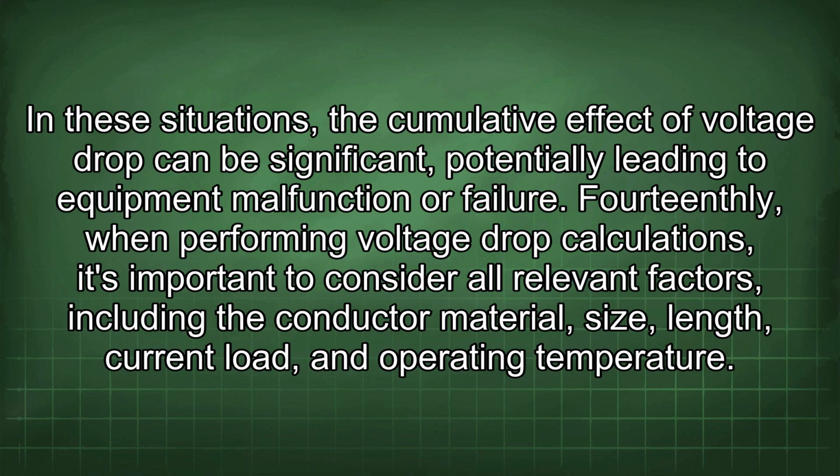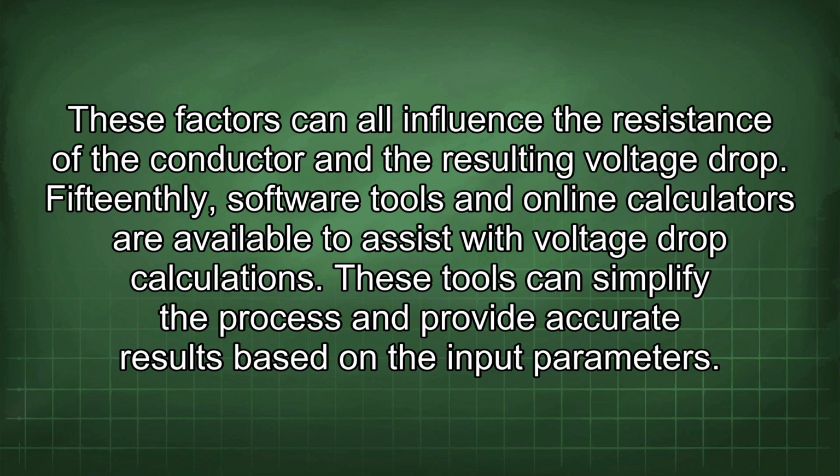14thly, when performing voltage drop calculations, it's important to consider all relevant factors, including the conductor material, size, length, current load, and operating temperature. These factors can all influence the resistance of the conductor and the resulting voltage drop. 15thly, software tools and online calculators are available to assist with voltage drop calculations. These tools can simplify the process and provide accurate results based on the input parameters.